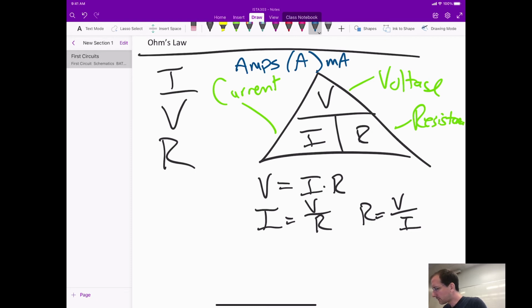Voltage is usually measured in volts. How much voltage is a lot of voltage? Well, in class, most of the circuits we're going to be making will be powered with 5 volts from the USB port. Most electronics run at either 3.3 or 5 volts, and computers, the ones that you have on your desk, usually use a variety of different internal voltages. CPU usually runs at 1.8 volts, 12 volts historically for motors and the hard drives and other sort of heavy things. But in general here, nothing that we're going to use is going to be much more than 5 volts.